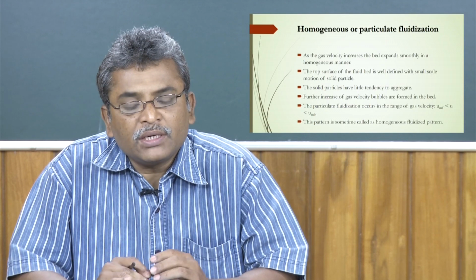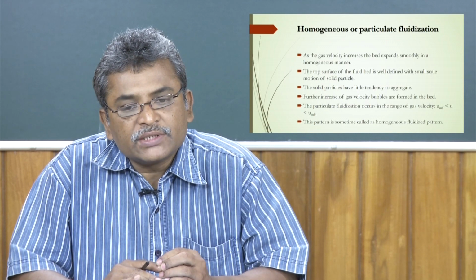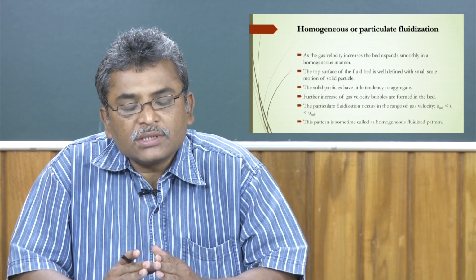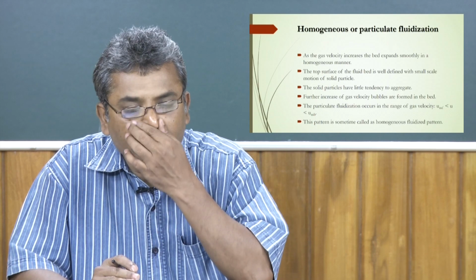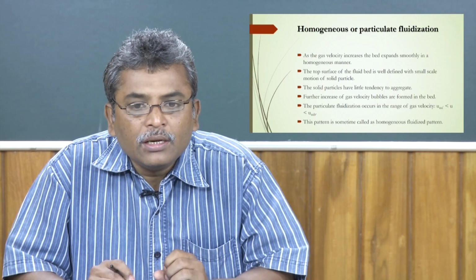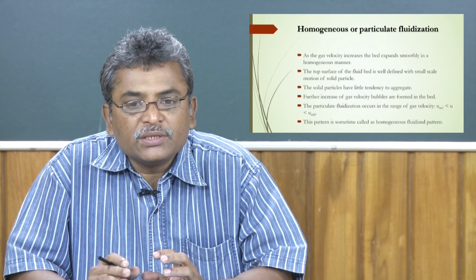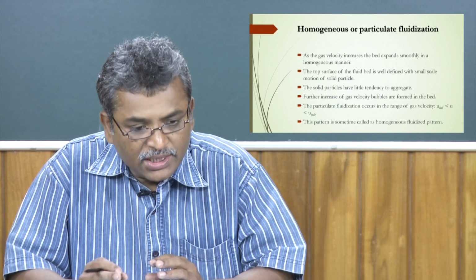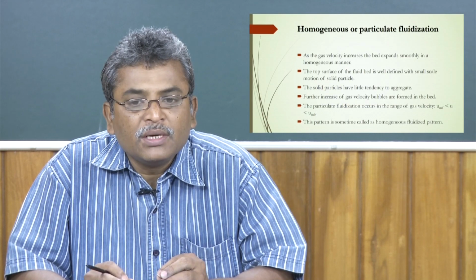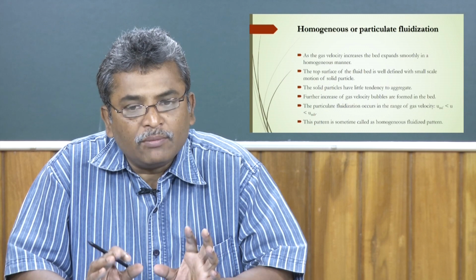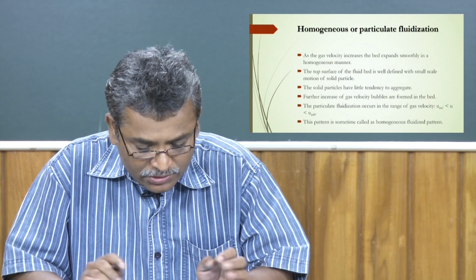In this particulate fluidized bed, with the same particle, you will see if you just change the gas velocity a little bit higher, there will be a change of phenomena from this particulate to the bubbling phenomena. Inside the bed there will be a formation of small amount of bubble, okay, small bubbles, and they will be going upward at a certain velocity.